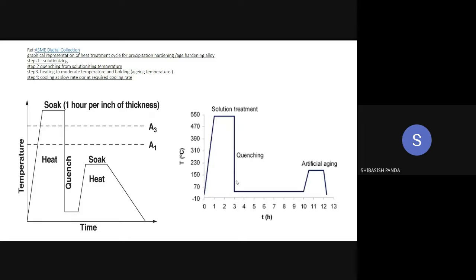What is the difference between hardness and hardenability? That's why I told you to go through the IPM, or at least I taught you. Hardenability means how easily you can form martensite throughout the entire cross section of the material. But hardness is the resistance to plastic deformation, which is measured by the indentation method. Please go through the tensile test part. Okay, fine. You understood now.